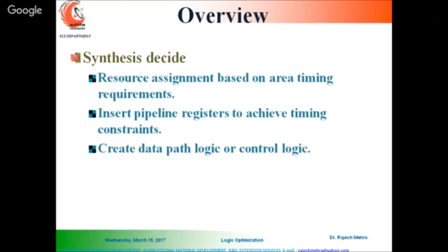And again, we can use pipeline registers. Pipeline registers are used to save already executed results. You have those ready-made results in registers, and whenever those results are required for different sections in your design, you can use them straight away from the registers. So we can say that these pipeline registers are also used to increase the speed of your design. These registers can be used along with your parallel architectures, or sometimes with serial architectures also.